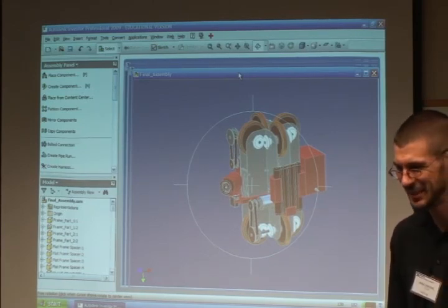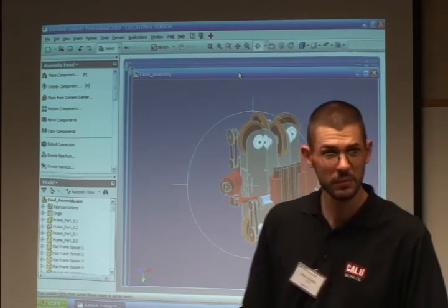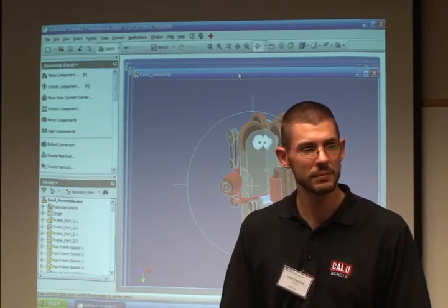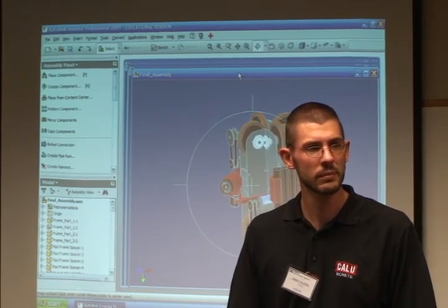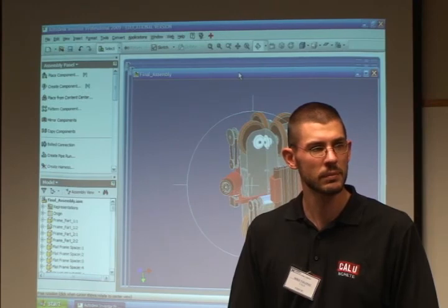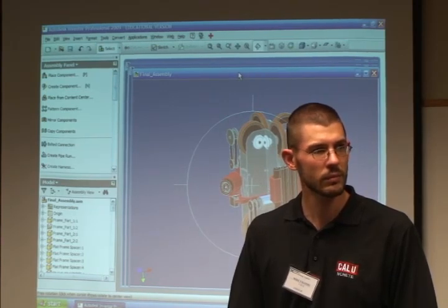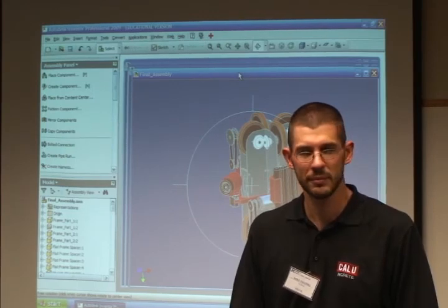So you always want to use a flat head, keep it flush with the surface, because probably sooner than later you're going to get a spinner that's going to come up and start taking those heads off. On the outer perimeter, inside it's okay to use a button head or a round head, but on the outside, keep everything smooth and flat. Not only does it look better, but it's a whole lot more effective. You might luck out the first time with someone not taking that button head off, but it'll eventually get taken off, and then you have to get the vice grips out and take that bolt out because it's snapped, and you only got 15 minutes, and those things add up quick.